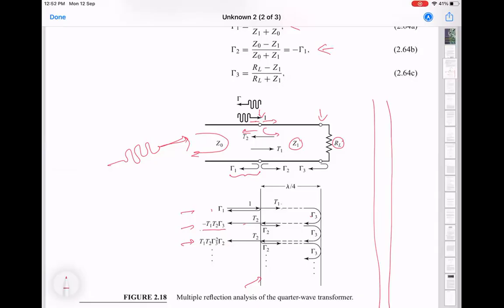So a 6 gigahertz frequency, let's say it was made for 6 gigahertz. When I send in at time t equal to 0, I turn the signal on. That is no longer a fixed frequency signal, right? Because it has this finite rise time. So that's another way of thinking about it, is that when you first start the 6 gigahertz wave, it actually has a finite bandwidth of signals around 6 gigahertz. That depends on how sharply it rises, and it has some kind of an envelope. This part, I hope you guys know. It's a Fourier transform idea.